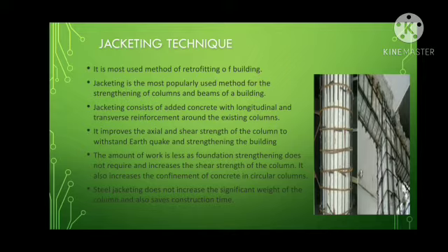The amount of work is less, as foundation strengthening is not required, and it increases the shear strength of the column. It also increases the confinement of concrete in circular columns. And steel jacketing does not add significant weight to the column and also saves construction time.